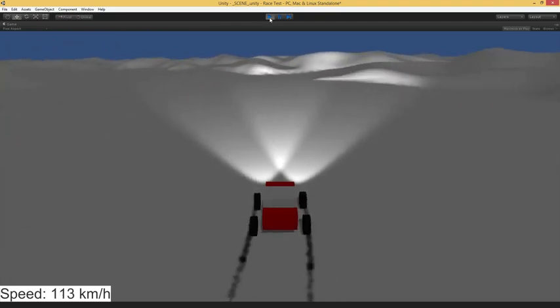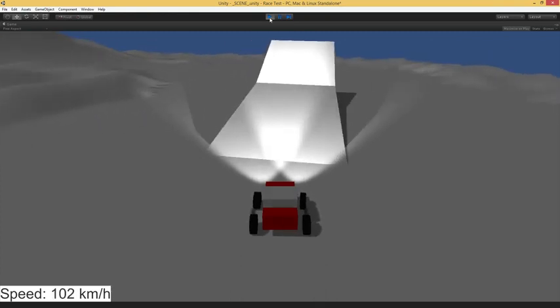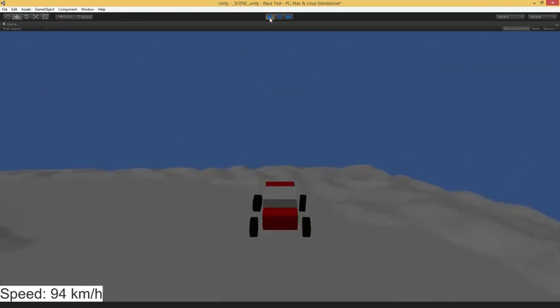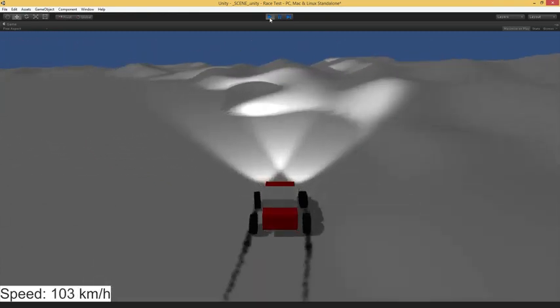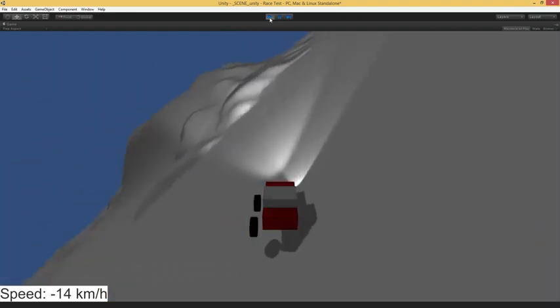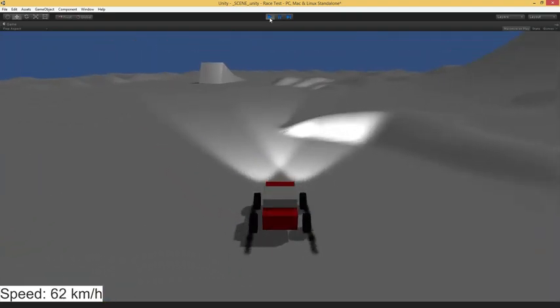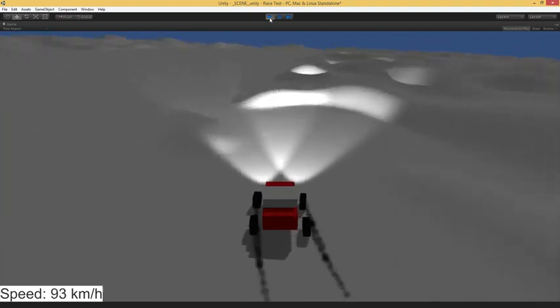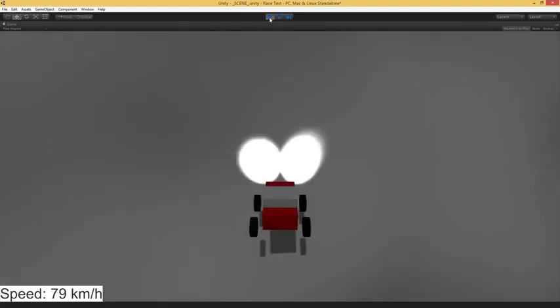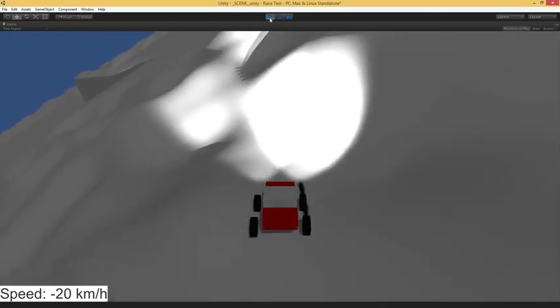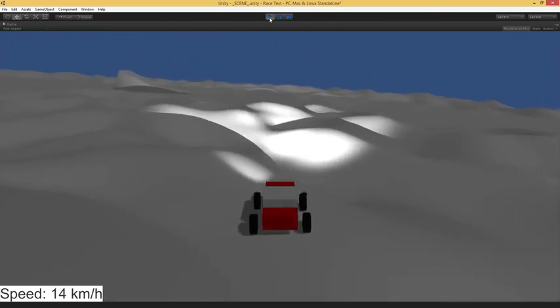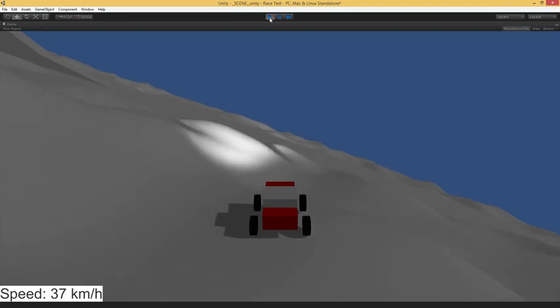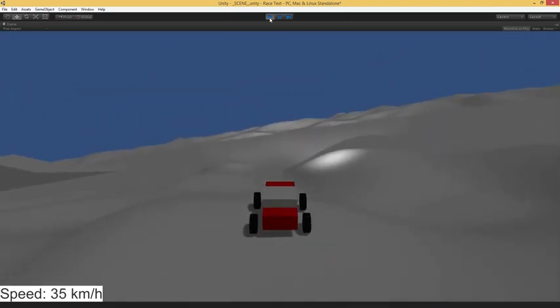But for something like this, I sort of made a toy box kind of thing, and I actually made this car work more like a remote control car than anything else. It's pretty good. This car has no gears, just one gear, and it's pretty forgiving to a lot of things. So that's the first thing you find out when you try to make car stuff in Unity: the normal physics colliders and rigid bodies aren't up to the job. You have to use wheel colliders.